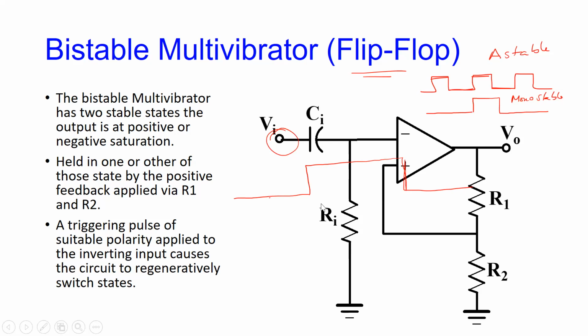And those are the three. Of course, you're more familiar with the flip-flop from digital electronics, the JK flip-flop or the type D, right? This one will work with plus or minus VSAT, so this is a bipolar type of flip-flop. These go from 0 to plus VCC, usually plus 5 or plus 3.3 volts alone. So that's a little difference, and all of them have applications around the place.